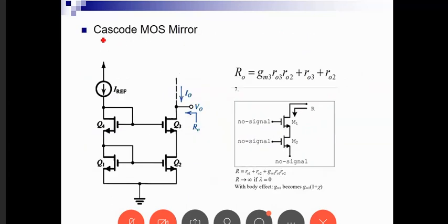So the first and most basic current mirror is called the cascode current mirror. We studied the regular current mirror, and it really looked like the lower half. The regular current mirror had two transistors, Q1 and Q2, and it fed my circuit. Exactly just like I had two transistors stacked to do the amplification, I can also have two transistors stacked to make the current mirror function.